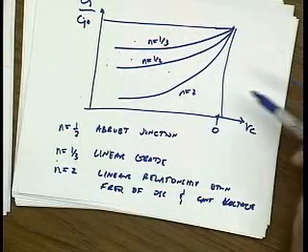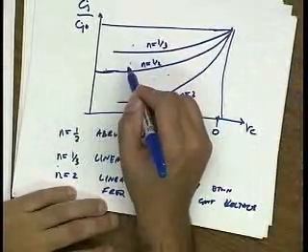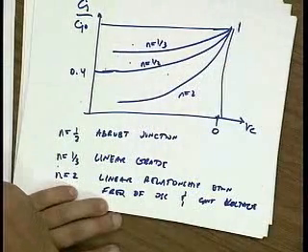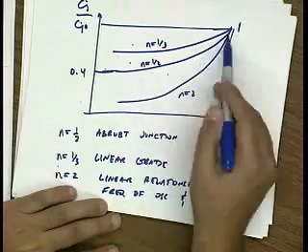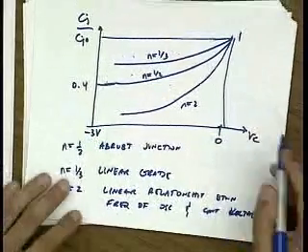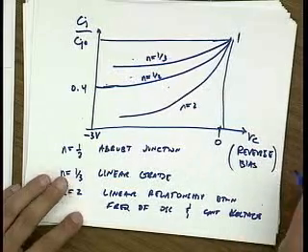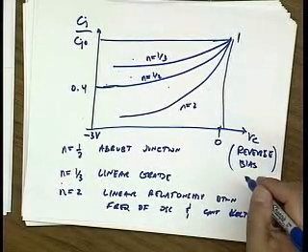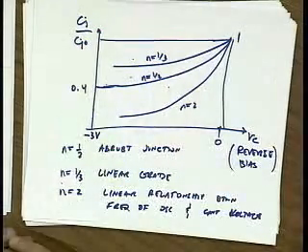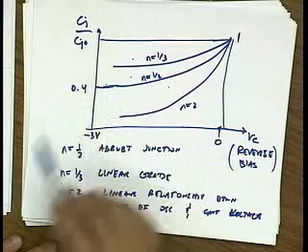And if you look at how much variation in capacitance you get, let's say even with N equals 1/2, I did a simulation or a simple calculation, and I saw that I could change the capacitance by something like 60%, going from 0 volts to, let's say, minus 3 volts, reverse bias. So this is the reverse bias. And so that's pretty good, but remember, the frequency is square root of that. So if I get 60% capacitance change, that's only 30% frequency change. And again, I'm making some very optimistic assumptions.